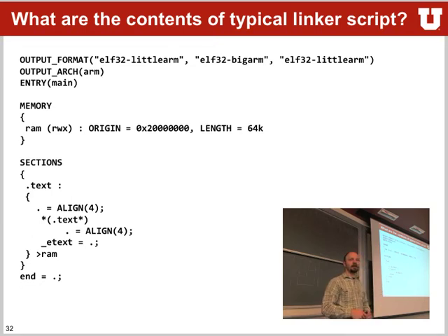As I said, this is an extremely simple one. We will look at more complicated ones later on and also in lab, where you can put things not just into RAM, but also into ROM. Usually into ROM, you only store things that are constant, so either executable or readable, but usually not modifiable, because modifying ROM is either impossible if it's burnt in, or if it's flash memory, you have to use specific functions to modify your flash. So usually, ROM is only read and executable, while RAM is read, write, and executable.